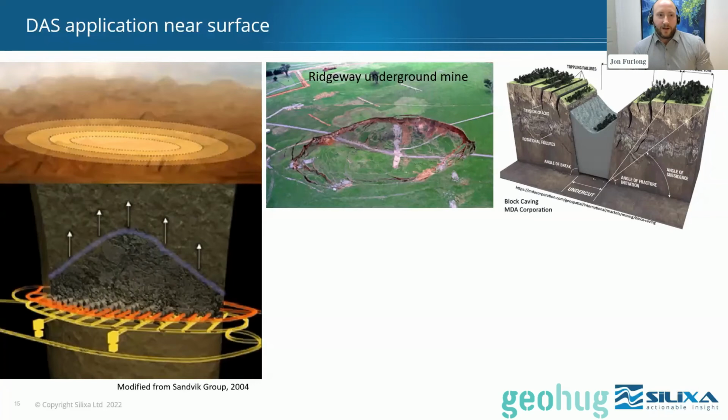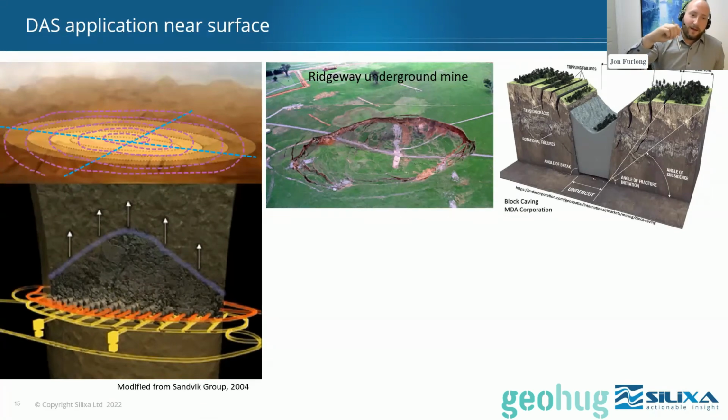So right now, obviously they're closed off. But if they start to behave erratically, it'd be great to know ahead of time how that subsidence zone is propagating. So we could instrument fiber in the top left here, just across your subsidence zone. But obviously, as that subsidence zone breaks away and subsides, you're going to lose that fiber. So you could also try a cinnamon bun type pattern, and that way, as the subsidence zone lets go, you're able to maintain fiber on the periphery. And that way we can hopefully image some of these subsurface tension cracks and fractures ahead of the subsidence zone.